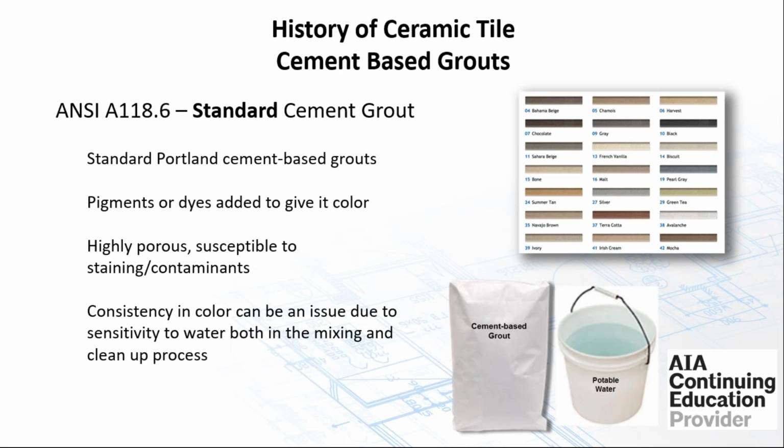With a Portland cement grout, there are a couple of things to be aware of. That is that it will be highly porous, and is susceptible to staining and contaminants. And it doesn't matter what brand of Portland cement grout, based on the fact that it is a Portland cement grout, some of the properties of it will allow for staining, discoloration, and such, and we'll talk about that in a few minutes.